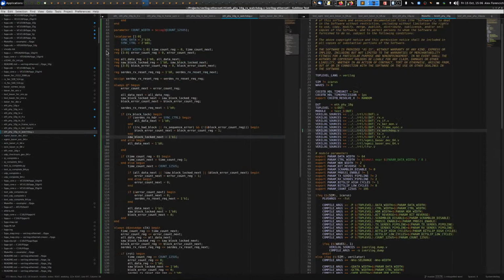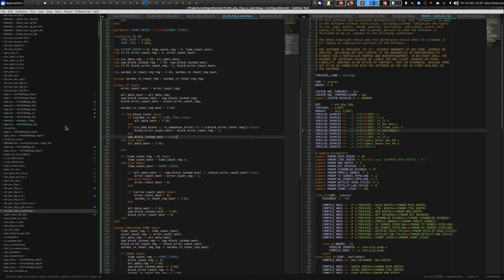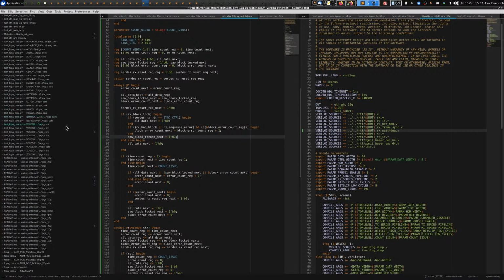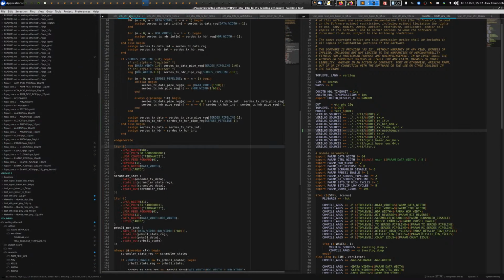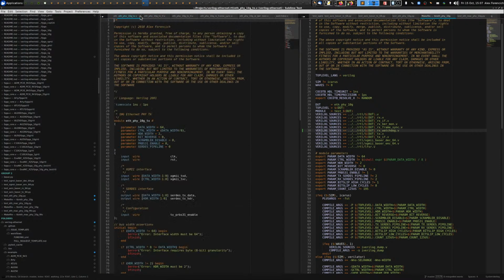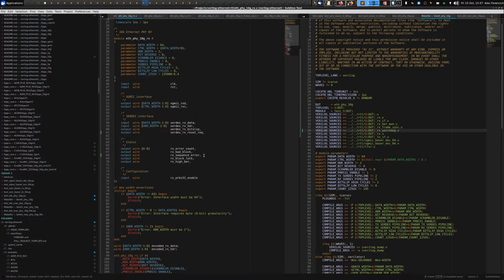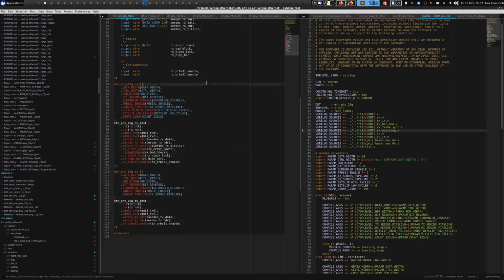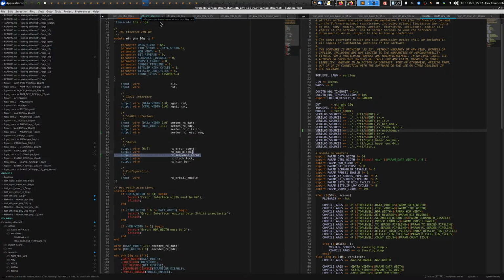Now that I have the reset request output, what I need to do is attach it in the design, right? So in this case, I'm looking at, well, let's see. So I have this in the IF. Did I pull this all the way up to the top of the PHY? No, I didn't actually. I need to add a couple more connections here, right? So this one I have, need to add sequence error output to the top level PHY, right? Bad block and sequence error. And then I also need to add the reset request output.